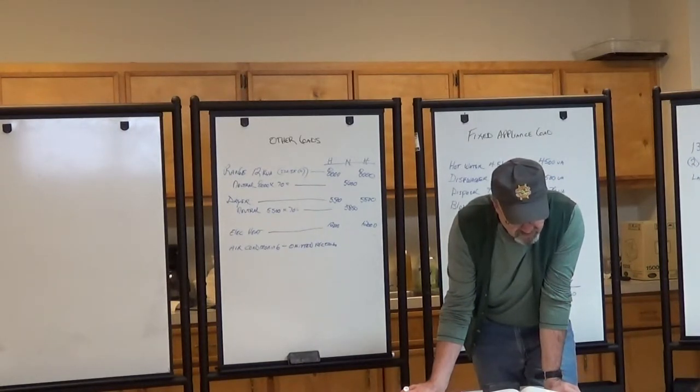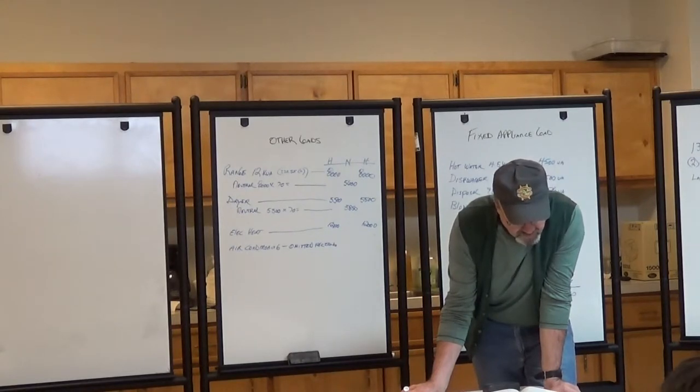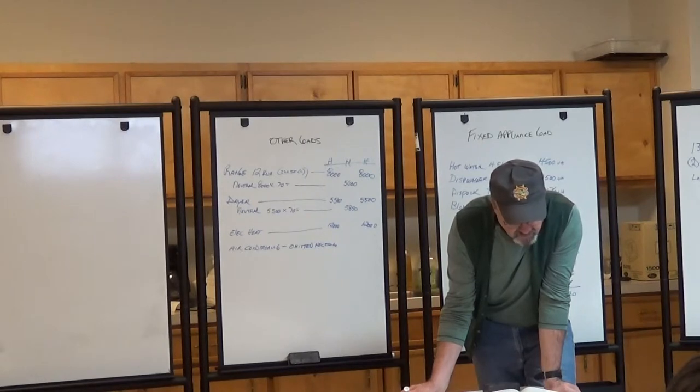So conductors supplying several motors or a motor and other loads shall have an ampacity not less than the sum of each of the following: 125% of the full load current rating of the highest rated motor as determined in 430.6(A); the sum of the full load current ratings of all the other motors in the group as determined by 430.6(A); 100% of the non-continuous non-motor load; and 125% of the continuous non-motor load.